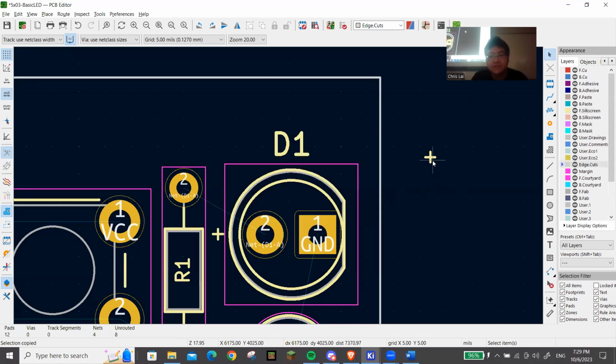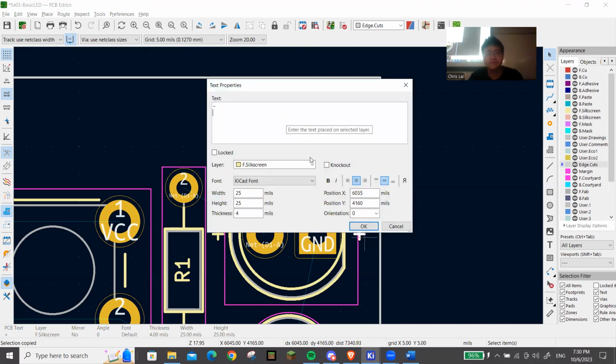What's up, Chase? Well, I was going to ask, if you have a schematic that you flip and it flips the text on the schematic, are you able to just flip the text back without flipping the schematic? For example, right here, I have the Arduino. I flipped it and flipped the text here. Yeah, when you flip that text, it goes to the other side of the PCB. So you can't actually flip it along the x-axis. It goes to the other side of the PCB, so it might be a different color. That's why. Okay. That's good to know.